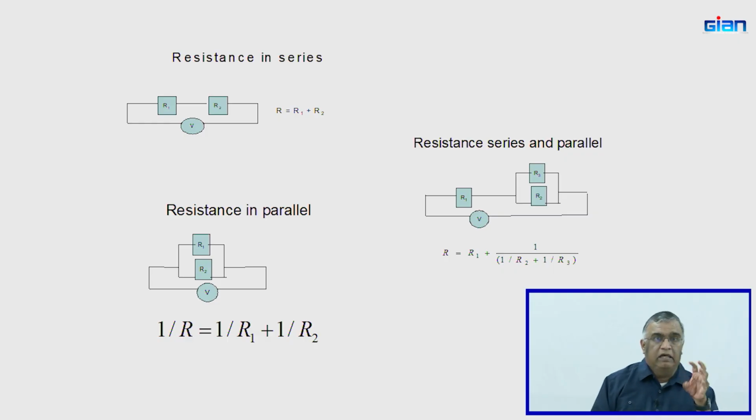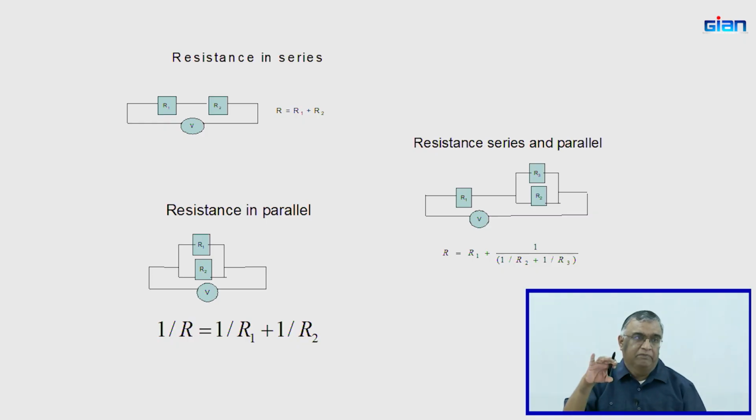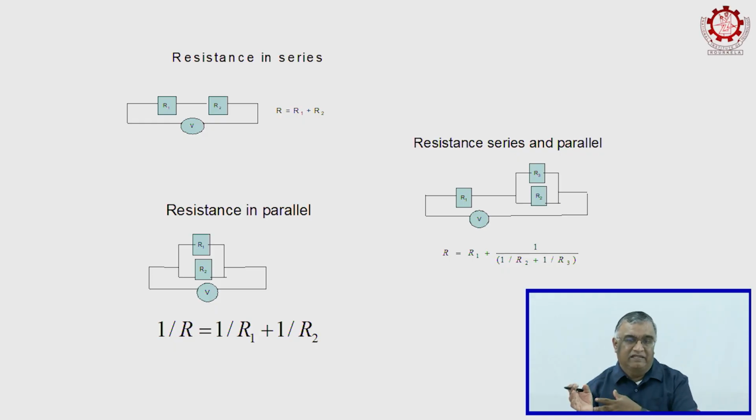The next one, we are borrowing some literature from the electrical engineering field, because ohmic heating is an electrical-based technology. That means you need to have some knowledge of electrical engineering, and the reason for this is just to show how the product is going to heat inside the ohmic heater. That depends on how the product aligns itself within the heating medium, or whether they align as resistances in series.